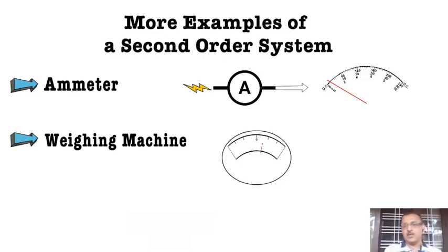So here it's not a unit step. The step input is of magnitude 75. So this you would see anywhere, like if you go to a grocery shop, and now those kind of weighing machines are not there. If you look at the weighing machine, the needle will oscillate. This oscillation is characterized by our 1 minus e power minus zeta omega n t by root of 1 minus zeta square sin(omega d t plus phi). So any instruments have this second order characteristic.